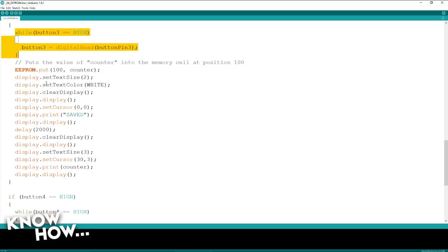Notice how when I hit the first button, it actually counts up really, really fast, right? If I have the write function, so writing to my EEPROM, set up the same way that I set up the counter, it's going to write hundreds, thousands of times if I just hold that button down. And it probably can't do that, right? It wears it out. I get 100,000 writes per cell. So it sounds like a lot, but if you mess up and have it in the regular loop, an Arduino can go through thousands of loops in a minute, and you could just kill all of the life of the cell. So I want to make sure that when I push that button, it only writes once.